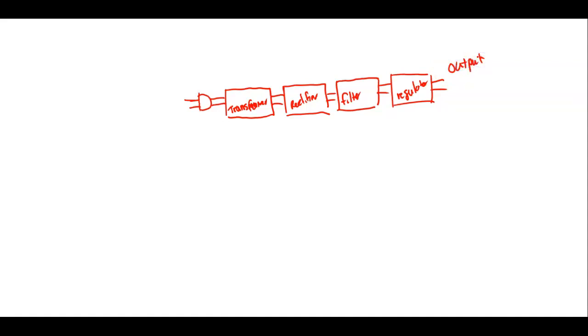And we could come over here and our power supply could end right there, right? Y'all understand? It could end right here if all I wanted was a half wave or full wave power supply. The more you add, the more expensive your power supply comes to. But electronic devices can't handle that. A light bulb, a resistive load can handle that. So if I was going to run a resistor or a motor, motors don't care, right? They don't care if it's filtered or unfiltered. They'll run off half wave or full wave just fine.